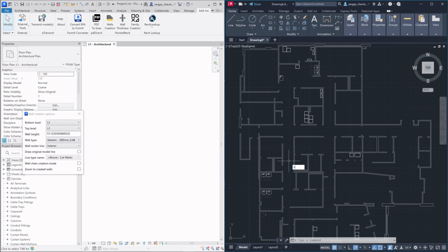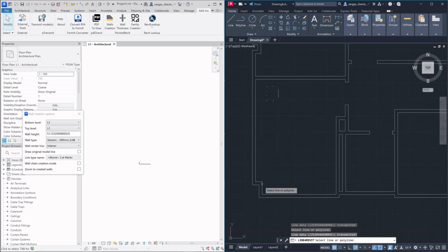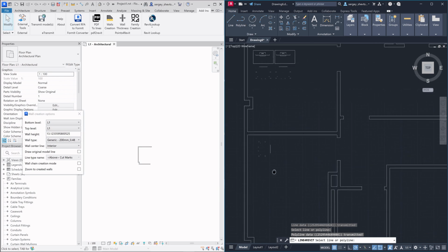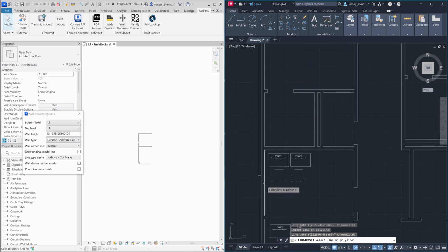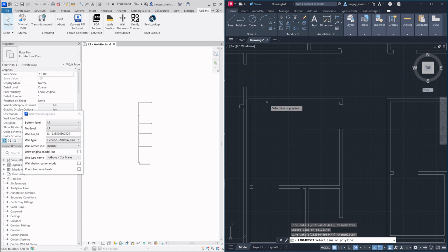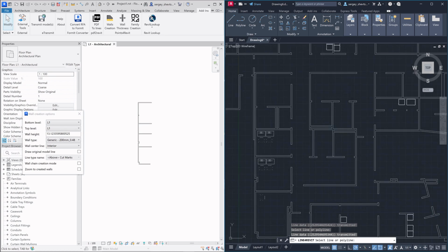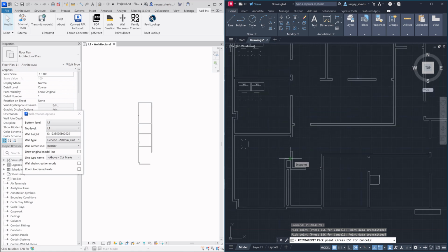When we select a curve, the CAD plugin analyzes the selected curve and sends all the vertices to the source file. The Revit plugin then receives these point values and creates a wall using all the vertex coordinates. It's quite similar to sending a single point, but instead of just one XYZ point, we are sending a set of points. This makes the wall creation process smoother and faster. But sometimes it makes more sense to use point picking. For example, if we have wall openings for doors, but don't need to create those cuts, we can use the Point4Revit command to simply pick points and create a solid wall instead.